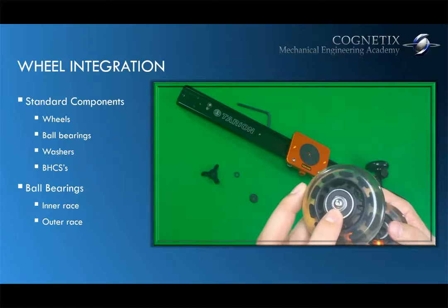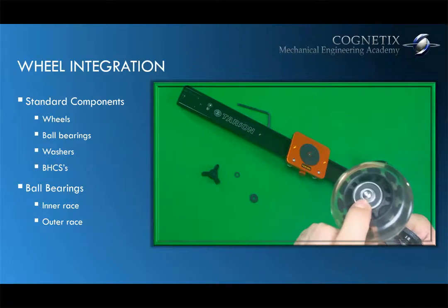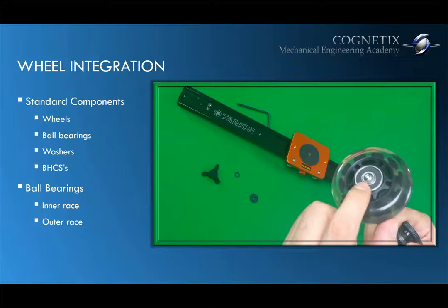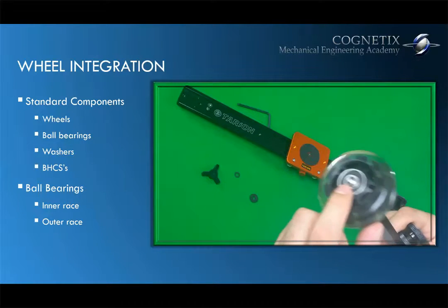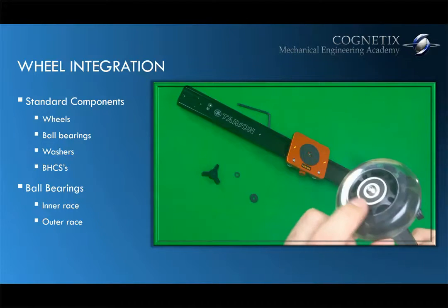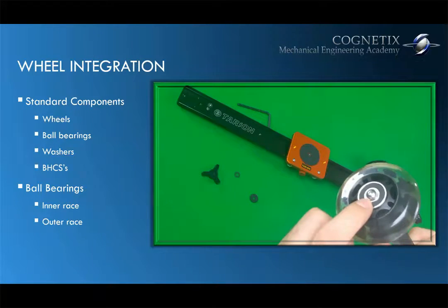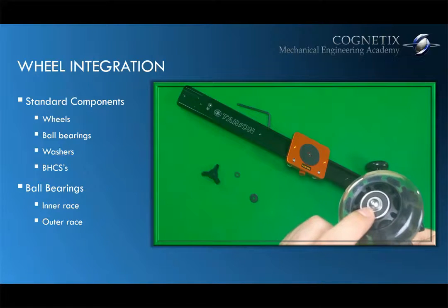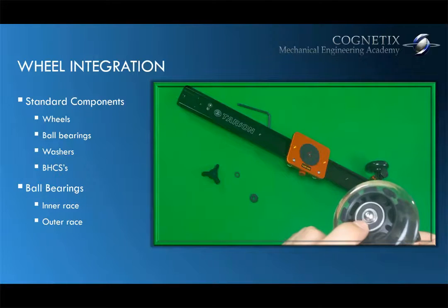The washers here, I really doubt that any company is going to go ahead and design washers. They just locate them, specify them in their bill of material, in their mechanical design, and integrate them. Now, a big part of the reason why there's a washer underneath this screw is so that the washer applies pressure to the inner race.